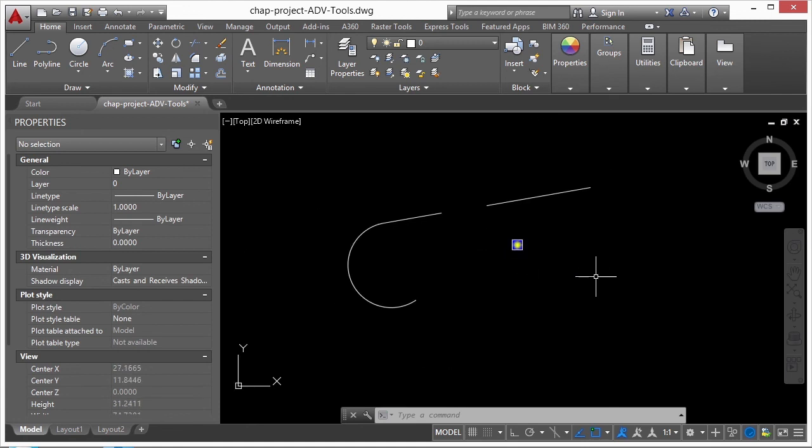We want to call it traffic light, so we're going to use the rename tool. We're going to use our measure and divide tools to evenly disperse these traffic light blocks across this line, but our line is incomplete. So we're going to use the join command and the polyline edit command to create one object that we can use our measure and divide tool on. If you do linear layouts like this, you'll use these types of tools quite often.